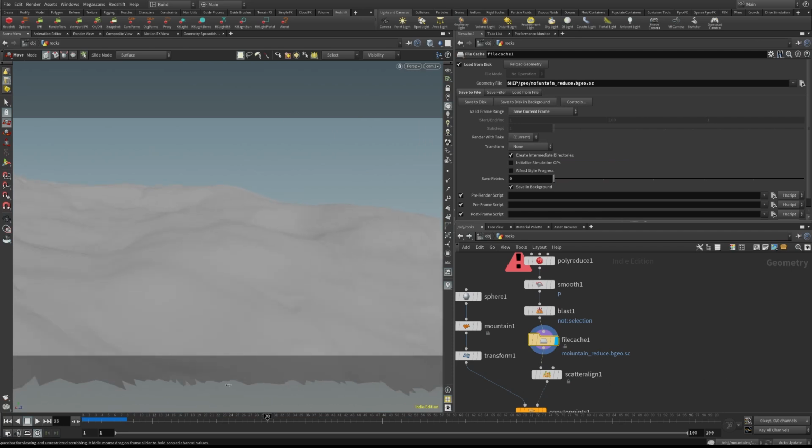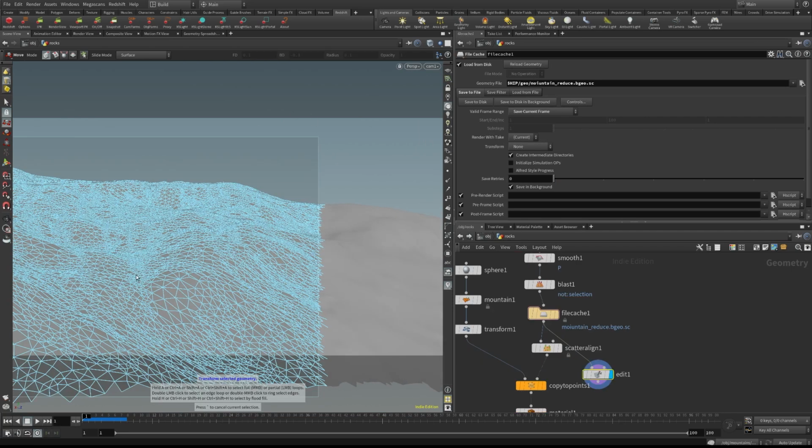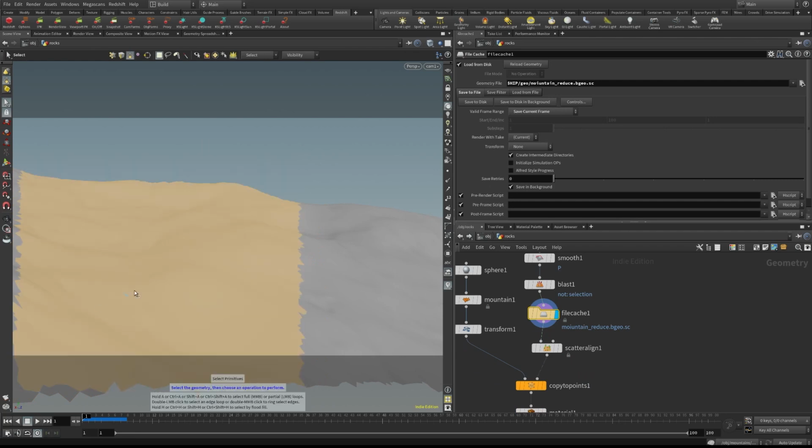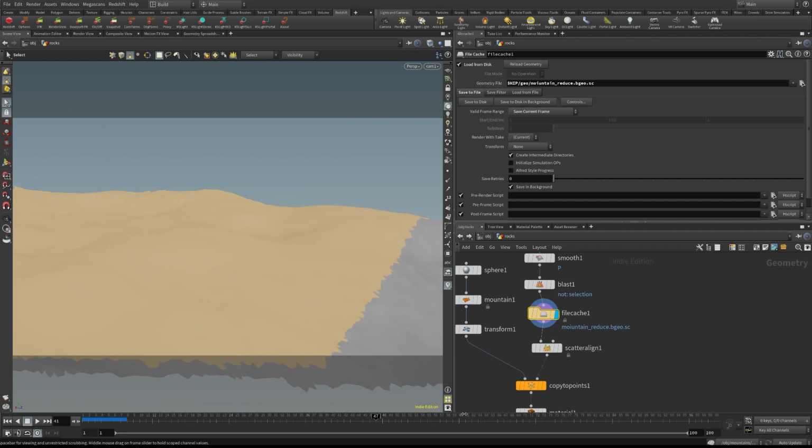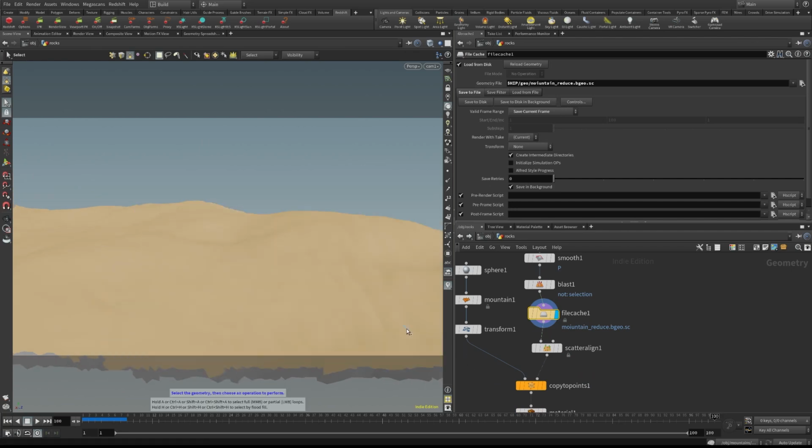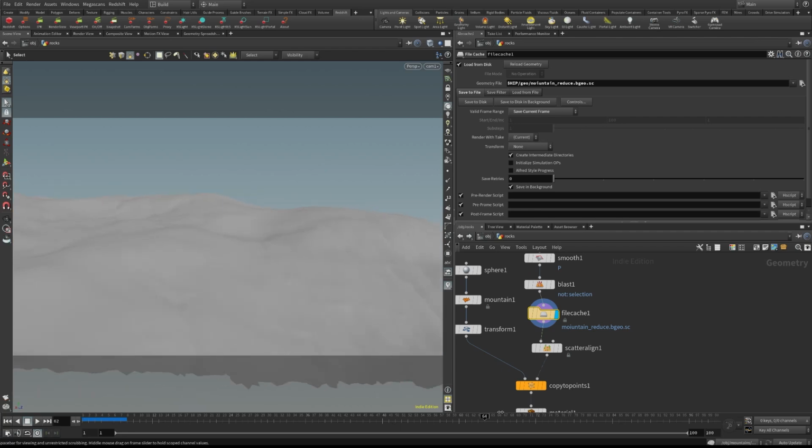As you can see, this is the camera movement. So I selected faces from the camera in the first frame, like so, and then added the selection in the last frame and blasted. So I will only have a distribution of plants and rocks where the camera will see it.